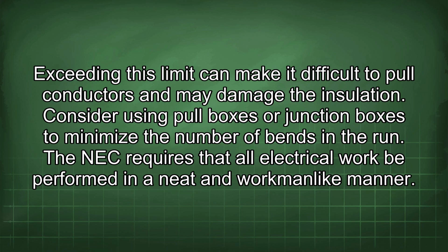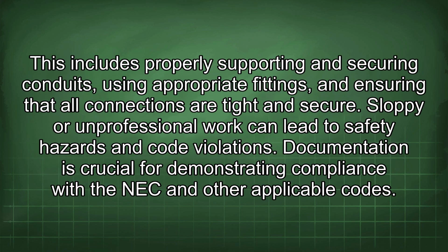The NEC requires that all electrical work be performed in a neat and workmanlike manner. This includes properly supporting and securing conduits, using appropriate fittings, and ensuring that all connections are tight and secure. Sloppy or unprofessional work can lead to safety hazards and code violations.